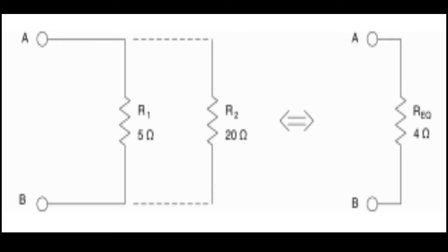If the second resistor is the same value as the first, the same amount of current will flow through each resistor. So the effect of adding a resistor of the same value is to double the current, or make the resistance half as much. If a third equal resistor is now added, the current will be tripled, meaning that the equivalent resistance is only one-third of the original. This relationship is valid for any number of equal resistors.